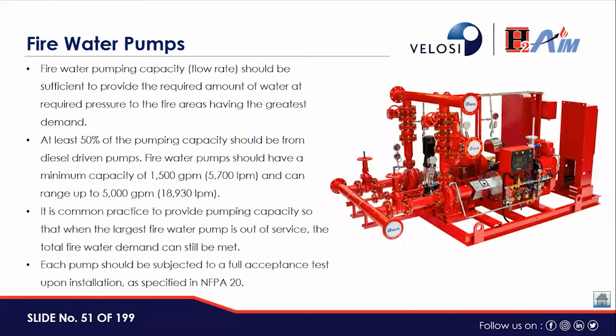It is common practice to provide pumping capacity so that when the largest fire water pump is out of service, the total fire water demand can be met. Each pump should be subjected to a full acceptance test, FAT, upon installation as specified in NFPA 20.